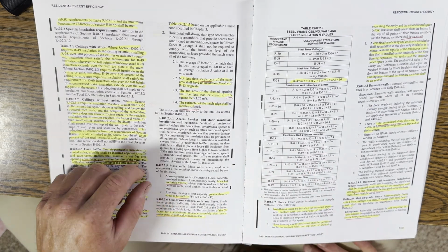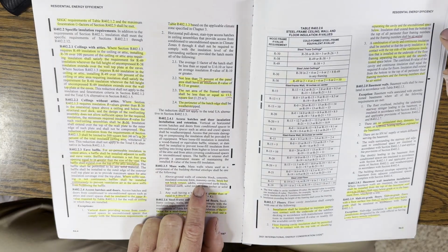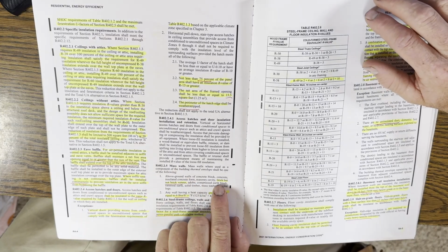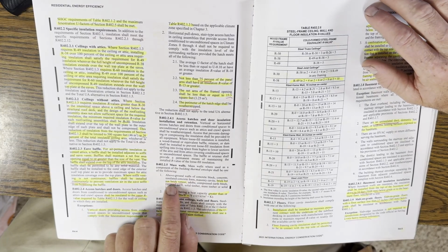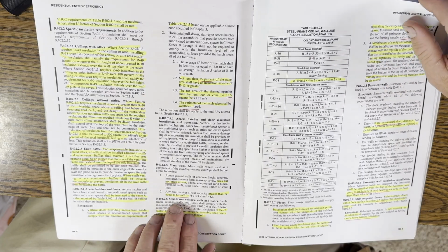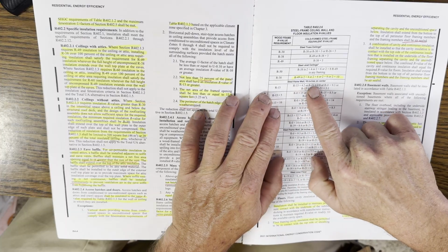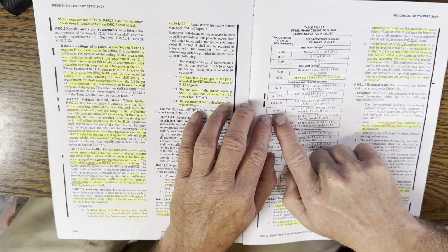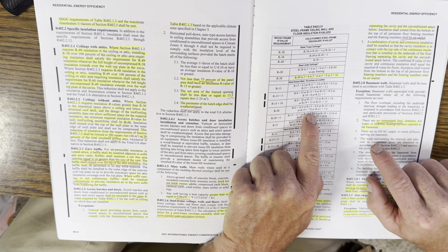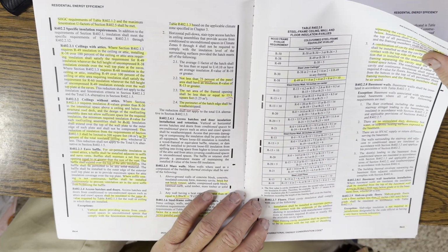They had a question on mass walls. The question was, which of this list of 4 items is not considered a part of mass walls? The answer is not brick veneer. You had a question on steel frame ceilings and walls. The question was steel frame wall 16 inches on center. It had an R20 normally, and I think the answer was R19 plus 7.8. I think that was the option you were given. That's correct.